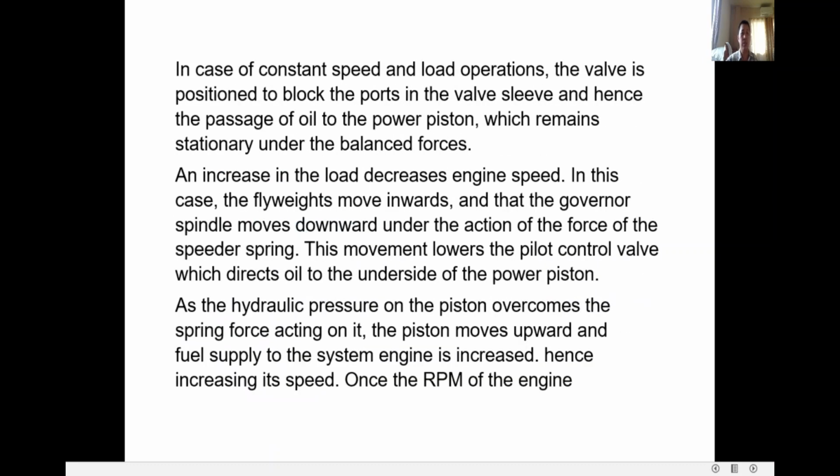So in case of constant speed load operation, the valve is positioned to block the ports in the valve sleeve, and hence the passage of oil to the power piston, which remains stationary under balanced forces. An increase in the load decreases engine speed. In this case, the flyweight moves inwards, as I mentioned earlier.